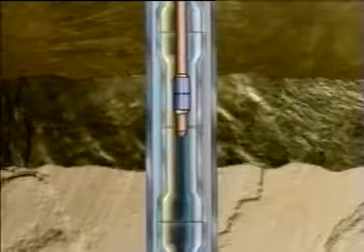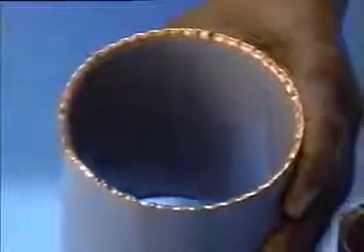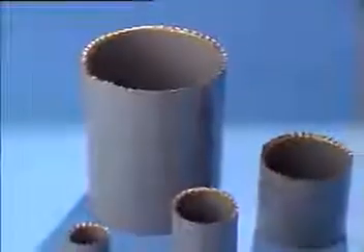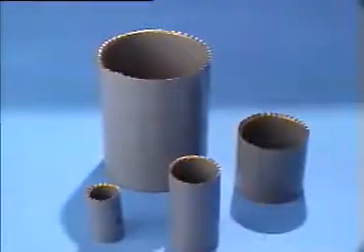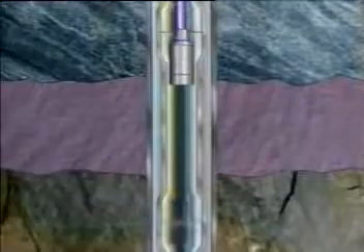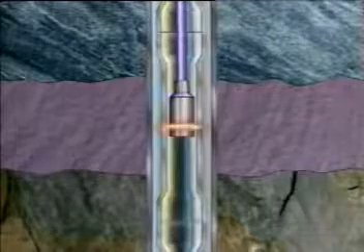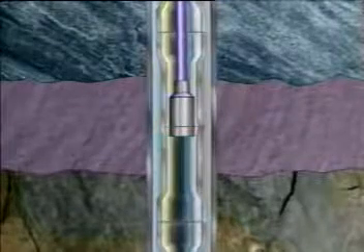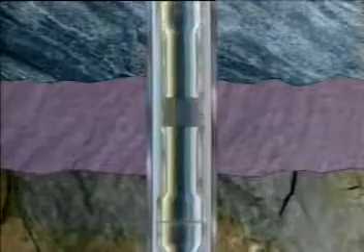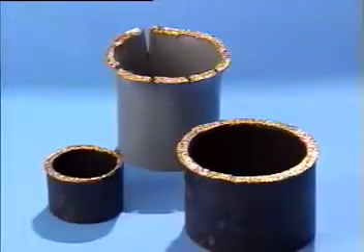The chemical cutter severs the tubing without leaving a flare or debris. This eliminates the need to mill or dress the top of the fish, making it easier to recover with an overshot fishing tool. Another cutting device, the jet cutter, severs pipe with a shaped explosive charge. Like the chemical cutter, the jet is matched to the size of tubing being cut. The jet cutter is also used to cut drill pipe, casing, and corroded or rusted pipe. The jet cutter leaves a flared fish top which must be milled or dressed off with a mill guide before the fish can be caught.